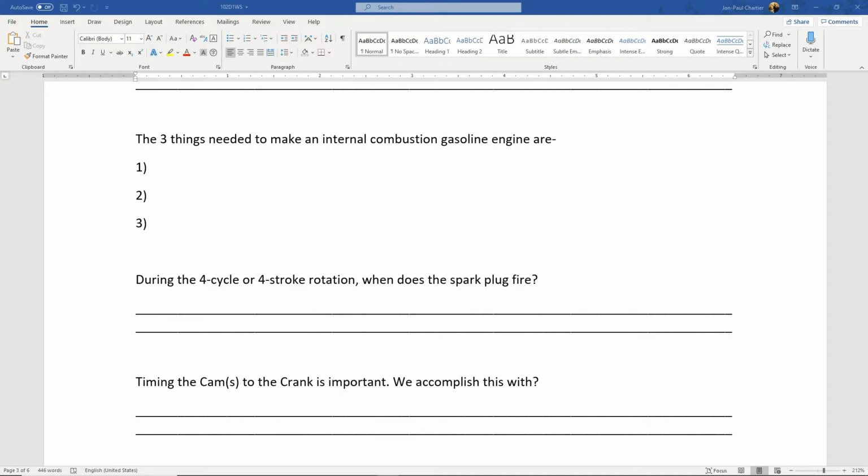And so the way that you go down your diagnostic branch is, I need to prove if it has fuel, I need to prove if it has spark, and let's talk about air. I've never really seen one not have air, if that makes sense.